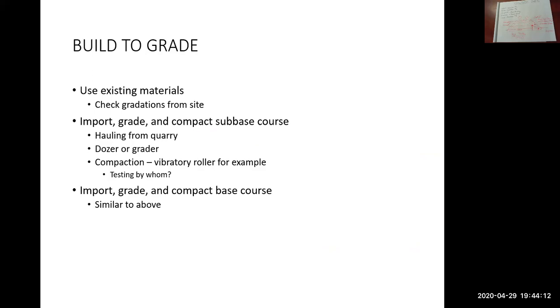Okay, so we've installed our utilities. Now our next major bullet is building to grade. So we've backfilled our utilities up to, say, subgrade is pretty standard. Again, subgrade is bottom of sub-base gravels. So building to grade.